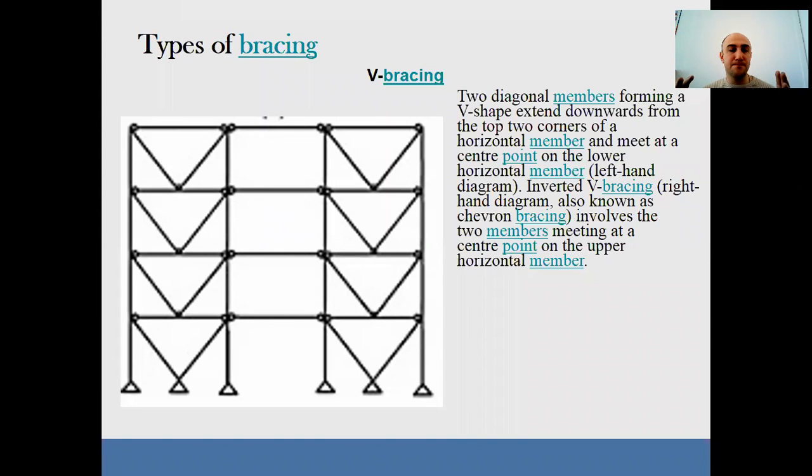The bracing members connect at separate points on the horizontal beams. This is like a link between the bracing members that absorbs the energy from the seismic activity through plastic deformations. Eccentric single diagonals can also be used to brace a frame.